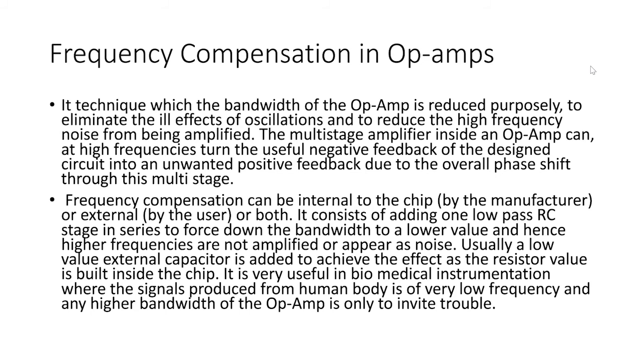The multi-stage amplifier inside an op-amp can, at high frequency, turn the useful negative feedback of the designed circuit into an unwanted positive feedback due to the overall phase shift through the multiple stages.